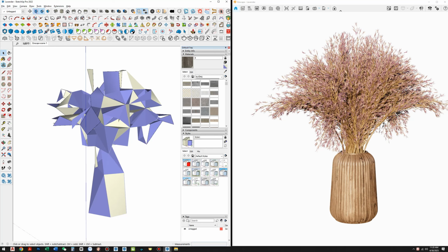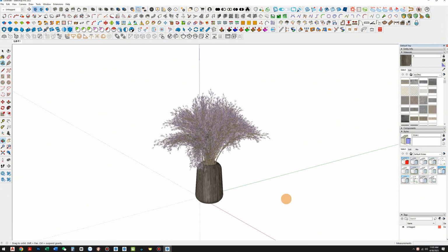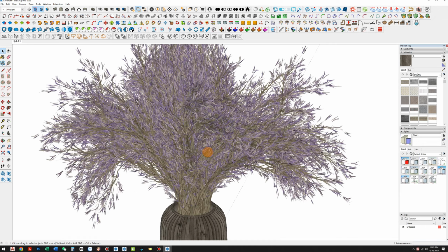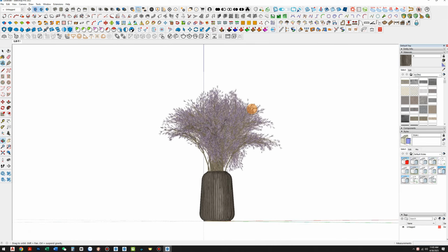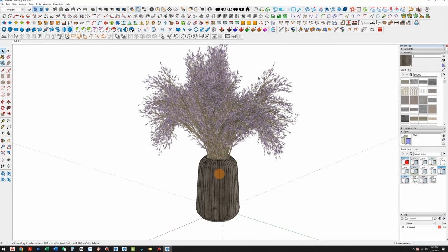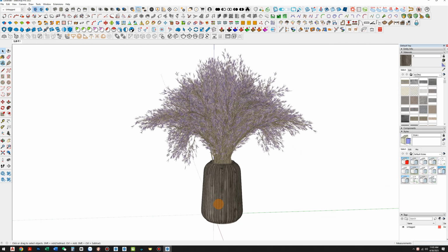Let's jump right in. Step 1. Convert your current file to FBX format. First, we need to check and ensure that your SketchUp model is complete and free of any issues. Double-check all objects and make sure everything is properly adjusted. Next, go to the File menu, select Export, and then choose 3D Model.